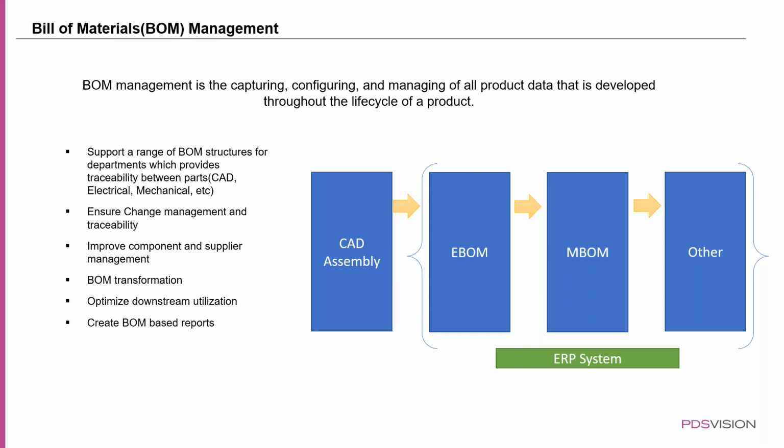We also have the possibility where a bill of material can have different types of data present in the structure, such as related documents and related supply chain data, such as the manufacturer parts and vendor parts. We can also have component management, such as alternates and substitutes, maintained inside these types of BOM.